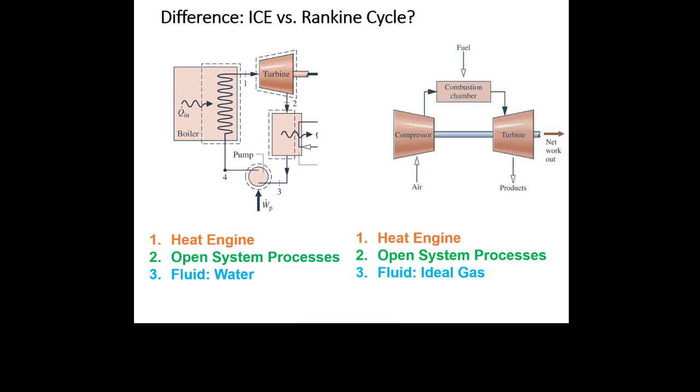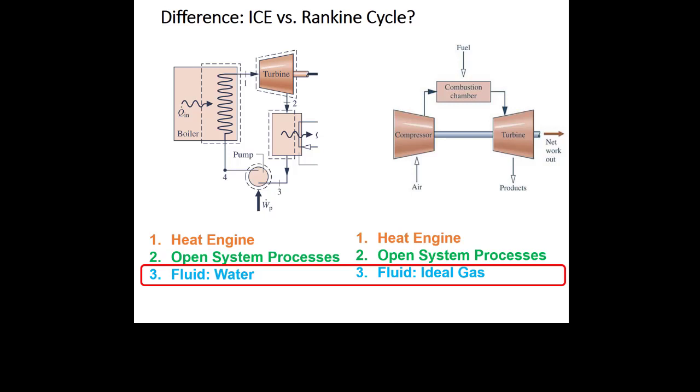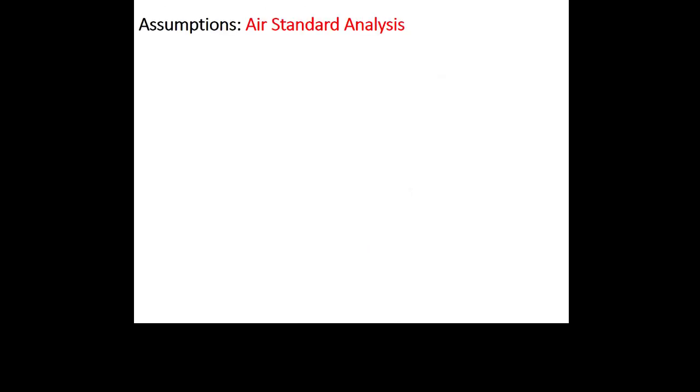So we'll use that isentropic efficiency to get the real outlet, right? So the difference here is it's like the Rankine cycle up until you're finished your symbolic solutions. But then when you start to put numbers in, the way you fix the states is different because the working fluid is an ideal gas.